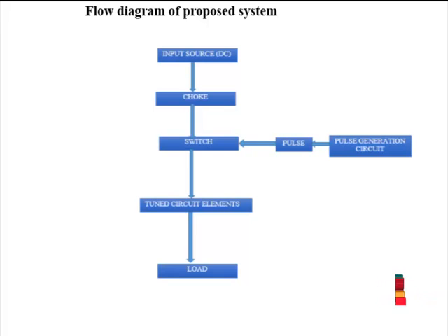These circuits are assembled from passive components in such a way that they only respond to a narrow band of frequencies. Applications include radio receivers, RF amplifiers, local oscillators, IF amplifiers, filters for frequency division multiplexing, and so on.